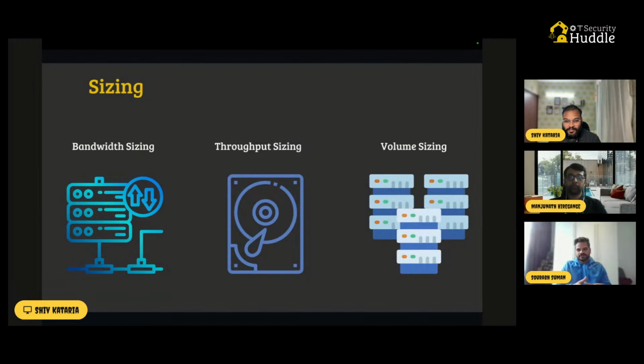So what is bandwidth sizing? Let's suppose you have a DCS network and it is on a 100 Mbps connection. If you start carrying all your data, all your logs on the same network, it might choke your network, and you will trip your own plant with the security solutions. But in OT, we have availability at the utmost importance. So you need to size bandwidth.